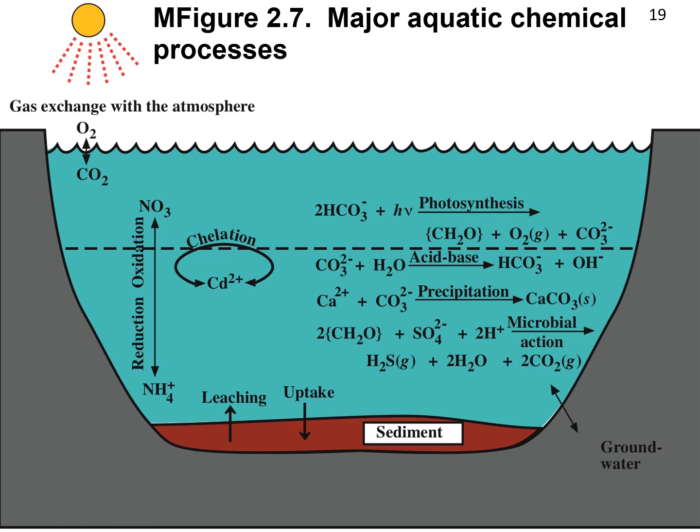For now, it's worth pointing out that in most cases within water, the things that we might want to measure are parts of dynamic processes, like equilibria, that make molar units the most convenient to work with. However, engineers hate molar units, and so most contaminant limits or design specifications will be given in mass percent units, or the closely related parts per million or parts per billion.